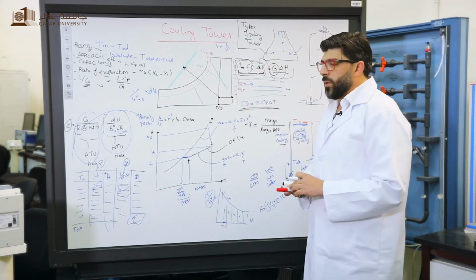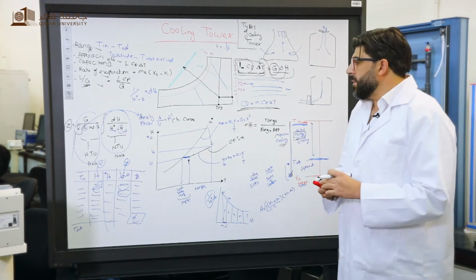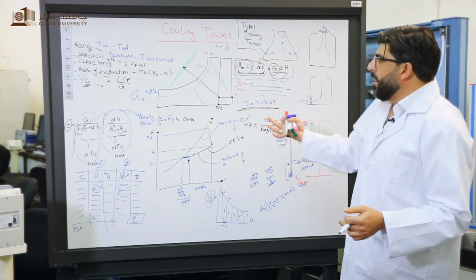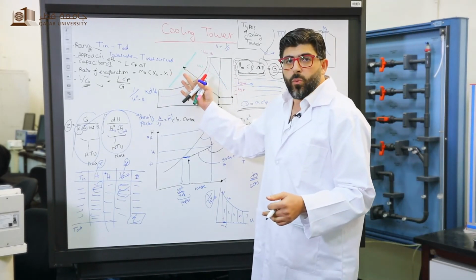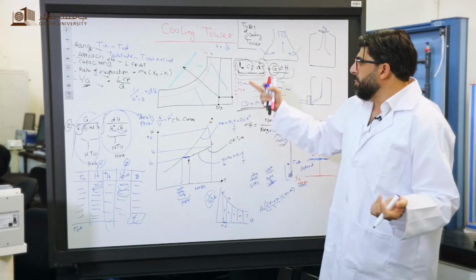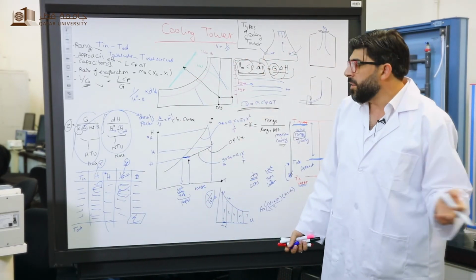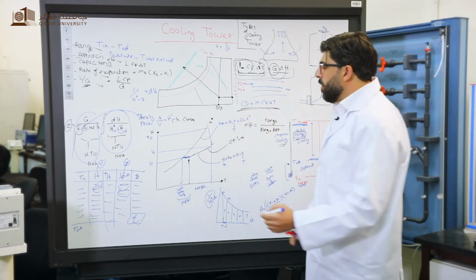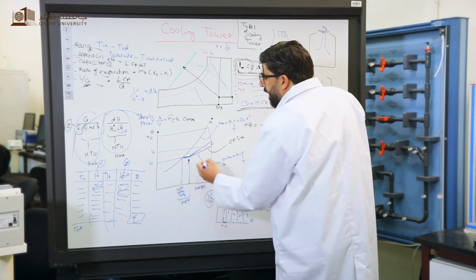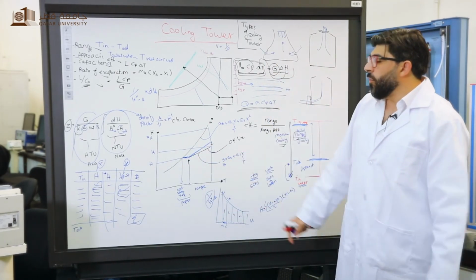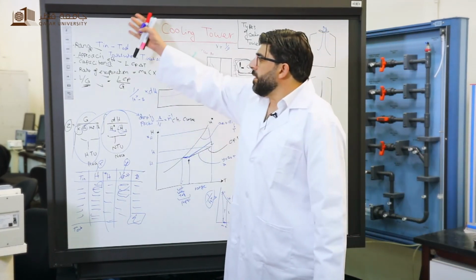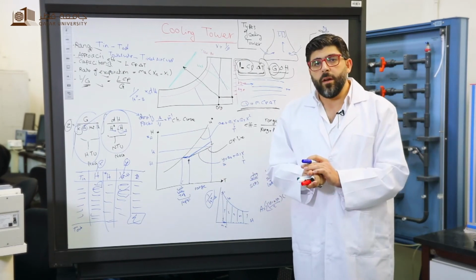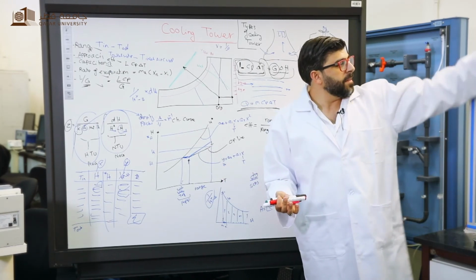Now in the experiment, we will do the experiment two times. You can use different conditions as you wish. You can check the effect of increasing water flow rate or water flux. You can check the temperature. You can check the gas flow rate. But here we will just test the water flow rate effect. So you will get 2 operating lines, and you study the change of water flow rate on all these properties of the cooling tower.